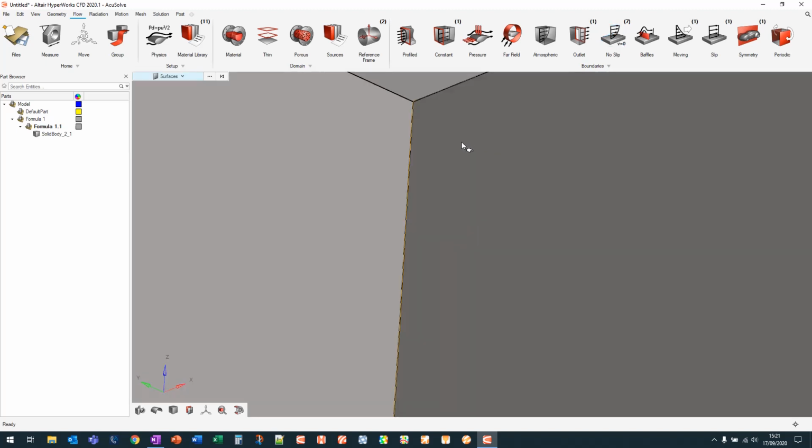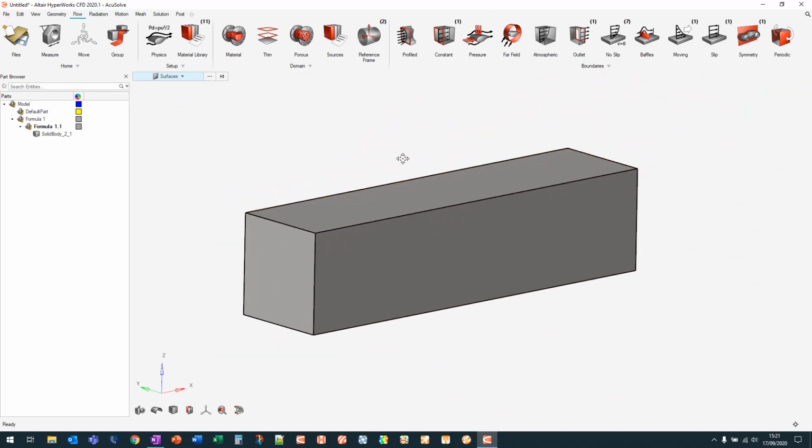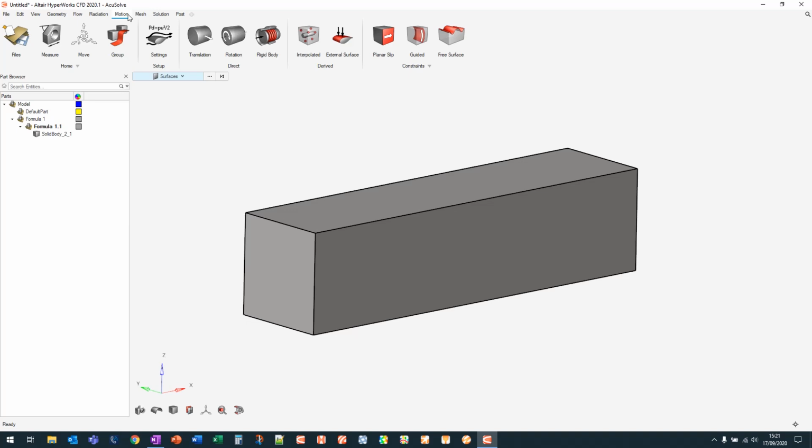Now that that's all finished, other things that we can do, again for slightly more complex simulations, is there is a level of mesh motion within here. So we can either fully specify the mesh motion or use an arbitrary Lagrangian Eulerian mesh motion approach, which calculates what the mesh deformation should be for you. And for example, you could do this for things like activating DRS. So rather than sweeping through different angles of attack as the DRS is actuated, you can transiently model this using a rotational function within here.